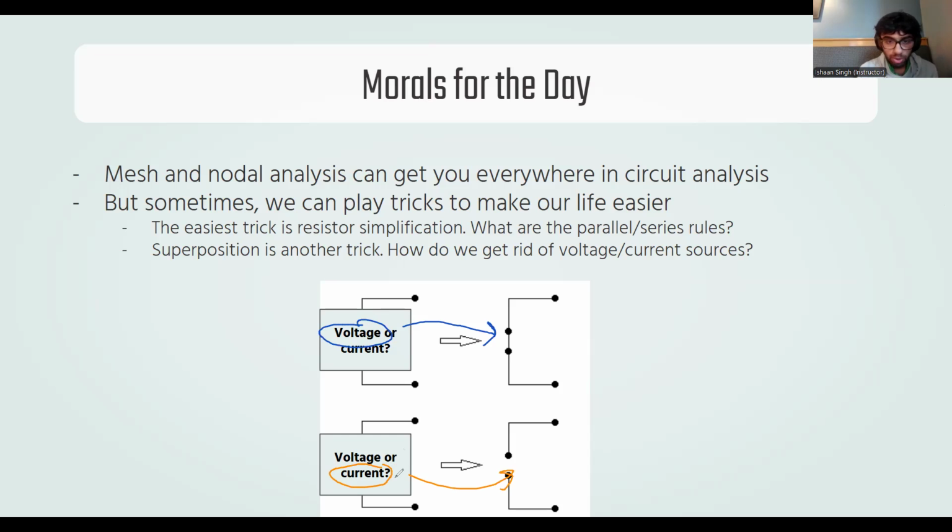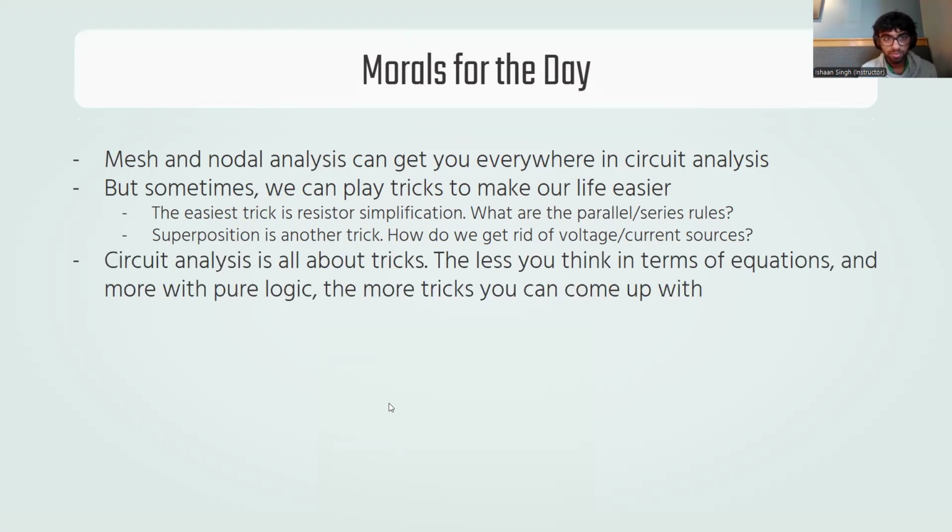Because remember, if I were to change a current source into a wire, that means a different amount of current could flow through there than what the current source says should flow through there. Okay, so that's not acceptable. And if I were to change a voltage source into a break in the circuit, that means there could be a different amount of voltage difference between these 2 points than what the battery says there should be. Okay, we're just trying to remove that source without impacting what else is going on in the circuit outside of this source. Okay. Voltage source at the top, current at the bottom.